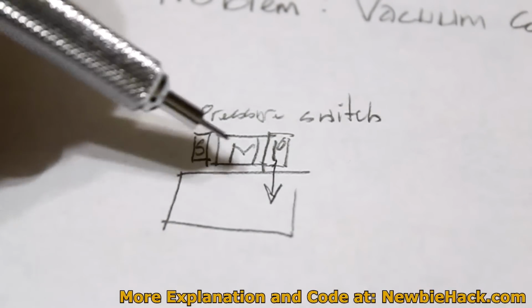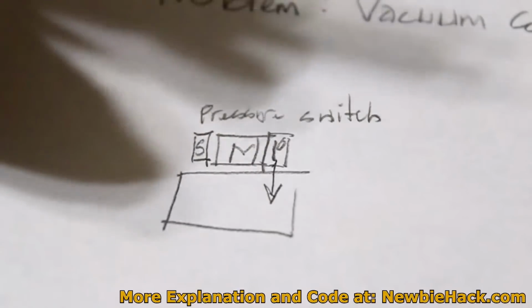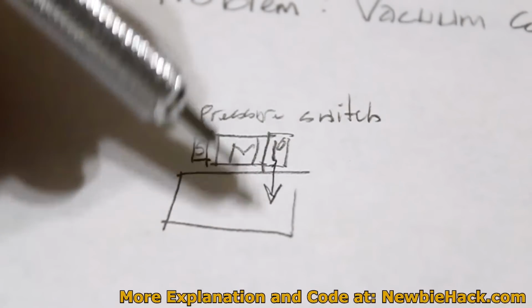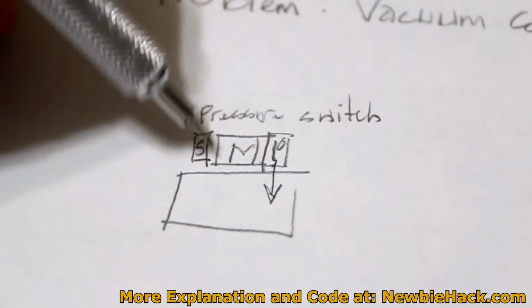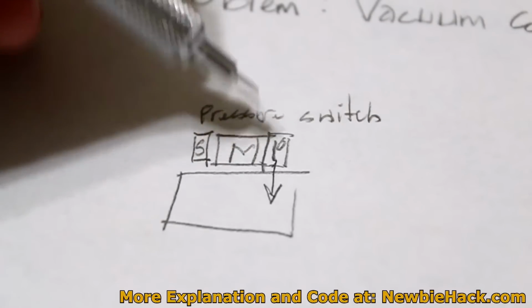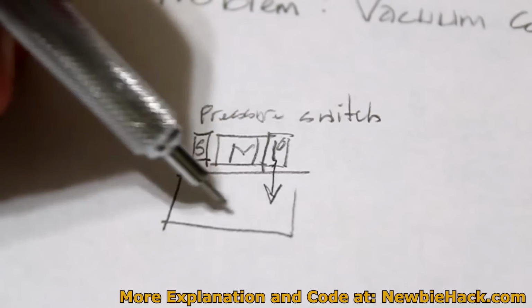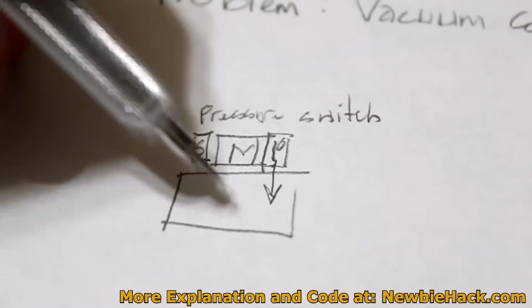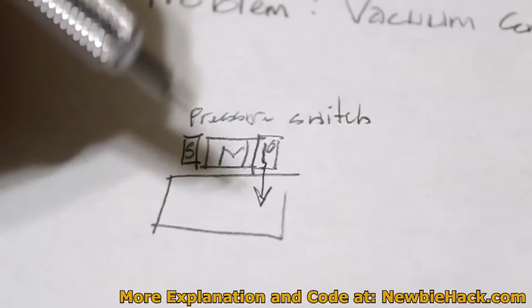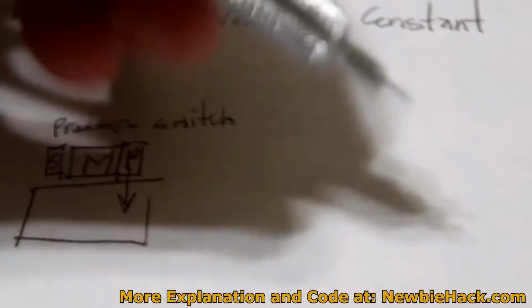And this is generally why you hear with compressors that are used in the construction industry for nailing or whatever, you'd only hear the motor every now and then. And that's because it's trying to maintain a minimum of 85 pounds per square inch of pressure in the tank. The challenge here is to make the vacuum work in a similar way.